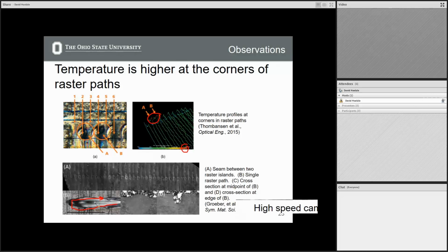And I think you can probably understand why: you're heating up the part as it goes along, right? So basically the melt pool trail is hotter than when you started, and then you're running the laser right adjacent to it on the way back. Okay, so you're hitting it pretty quick, in a pretty short period of time, you're hitting it twice with a laser. So you essentially preheated that region, then you heat it again, and so therefore it's going to have a higher temperature. Okay, so then the melt pool expands.